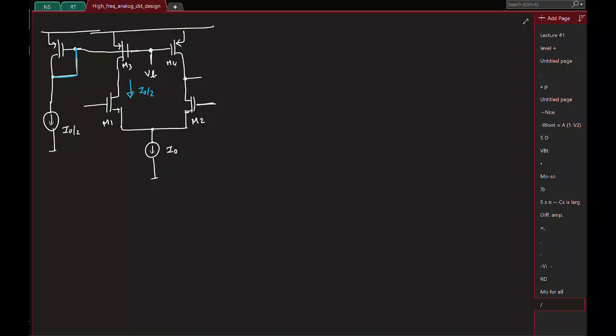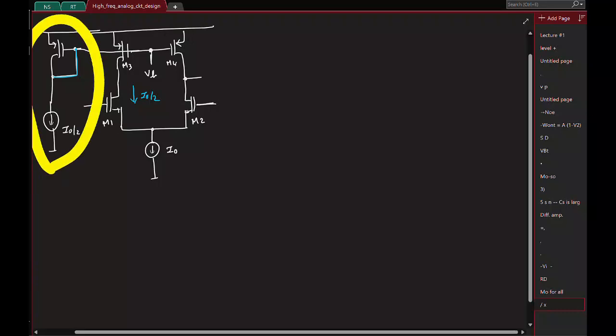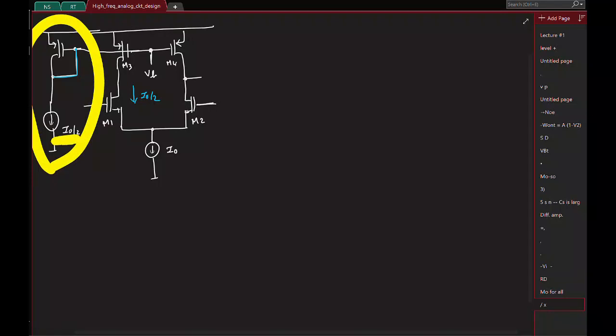Great. So now if you notice, okay, let me mark it here, maybe I0 by 2. If you notice, you actually don't need to have a separate branch like this. So if you think about it, this branch, all it requires is a current I0 by 2 and a PMOS transistor. So if I see, in this branch the current is I0 by 2 and you already have the PMOS transistor. So you can make this connection directly here itself. Is that logic okay?